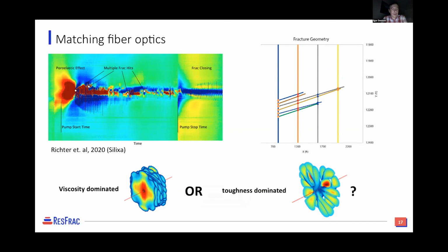Thanks for the question. Yes, it is different, because when you do enrichment in XFEM, or extended finite element, you add shape functions to it. So basically, you allow a discontinuity within an element, but you don't actually add different properties within this element. Here you have different properties, different layers, while there you just allow some sort of discontinuity, like a crack, within the element. It is maybe close, but not the same.